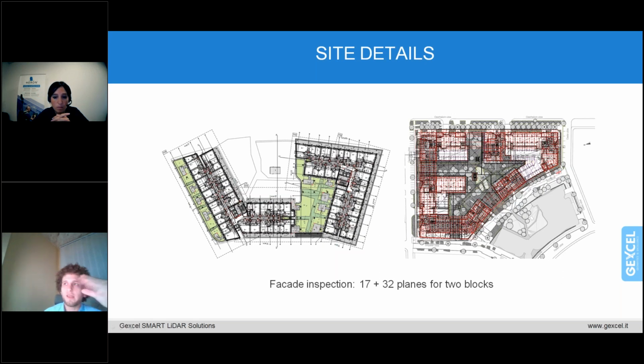So let's say we had all the things together: field to BIM, control geodesy, main reference network, stakeout of certain critical elements on the site within the same company and within the same team. Also the geometric control, which we would like to see now.